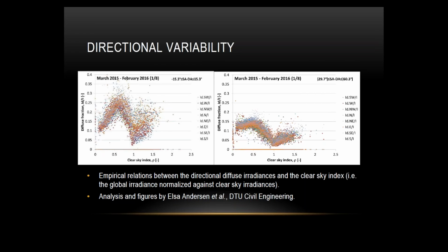When we step in the azimuthal direction from 30 degrees to 60 degrees, we also see an effect of this circumsolar irradiance increasing with a maximum at around 0.5 of the clear sky index. Another thing that's interesting here is this seems to be fairly independent of the direction of the opening. So you see you have here the points from all 8 cardinal directions. It's not exactly north, east, northwest, it's a little beside that, but you see there's not much difference between those.